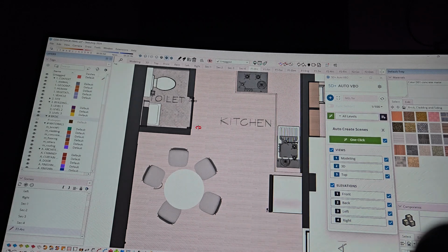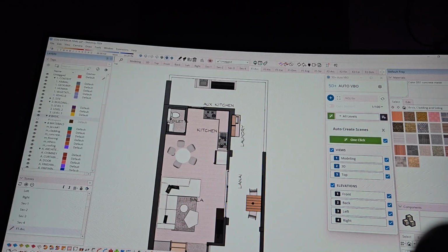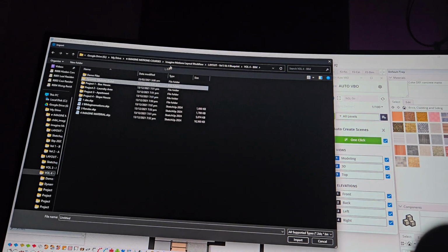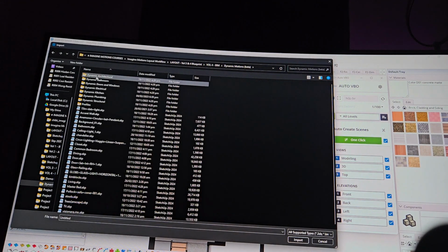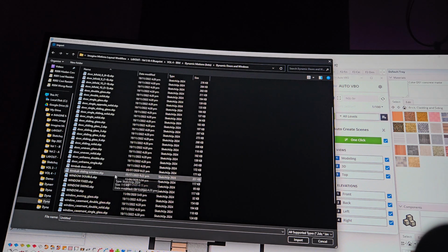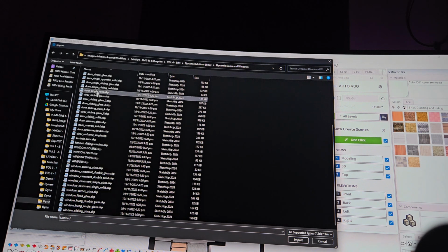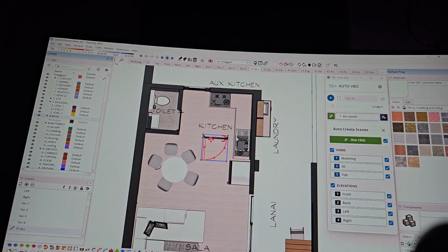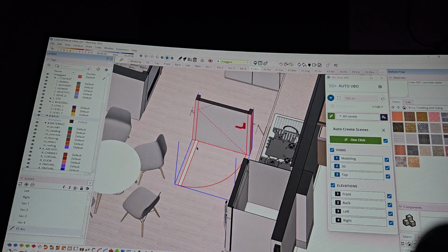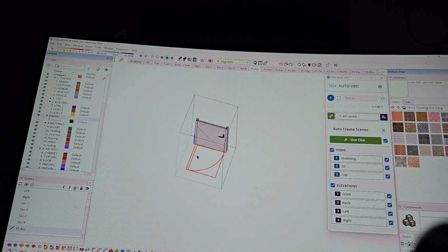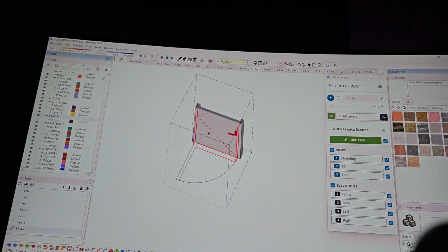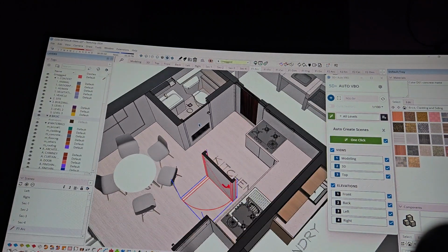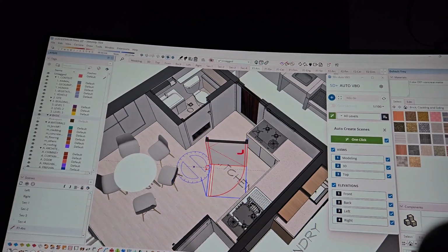I don't know where it is, but if you load a dynamic component, let's look for one. This is why I told them to use our workflow. So anyways, in volume 4 dynamic motions, dynamic doors and windows, let's get a swing door. So door single solid. Okay, if we load that into the model, this already comes with 2 tags. This tag is the 2D graphic that shows in the floor plans, and this is the 3D object that shows in elevations. So if we replace that with this bathroom door, let's try to do it.